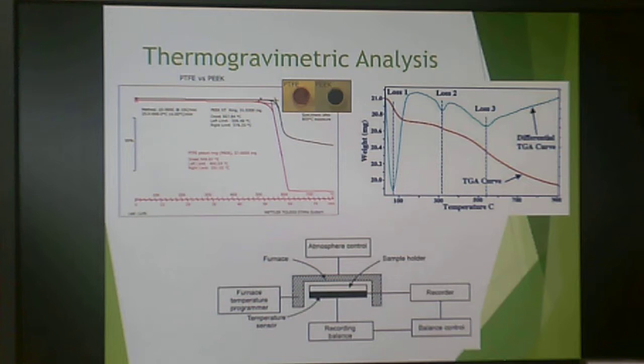It's really important to know at what temperature your material degrades when you're choosing a material. You need to have something that withstands the type of temperature that part might endure. So if your part is going to be enduring, say, regularly 350 degrees Celsius, you want to make sure that material can withstand that and doesn't break down. And that's a way to do that.